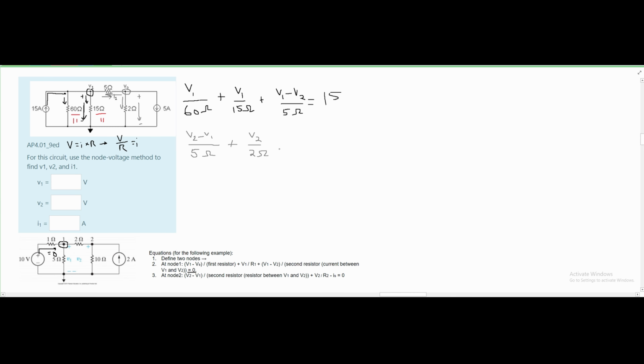And then after we do this, we have to subtract the current going through. However, we're still not subtracting. This is another difference between our example problem and our given equation. So in here, it says to subtract the current. That's because the current is going into the node like this. However, for our problem, we can see that our current is actually going away from our node. So that means we're going to have a plus 5 amps, and that is equal to 0.